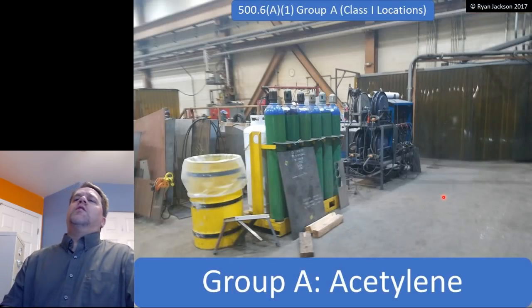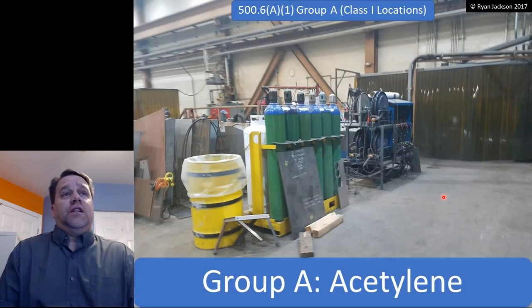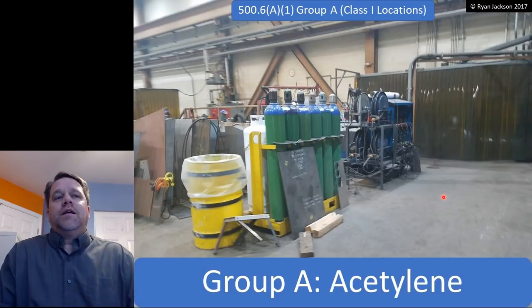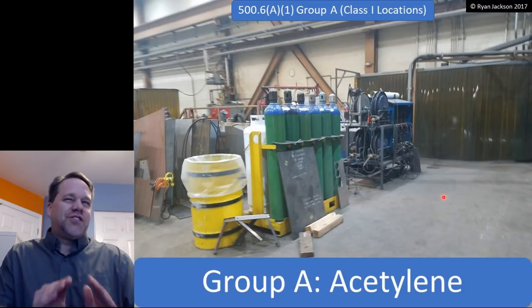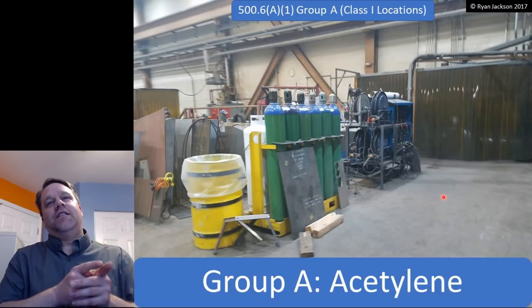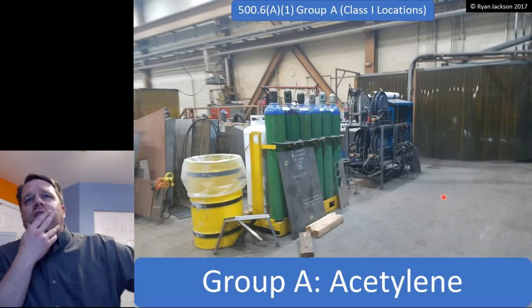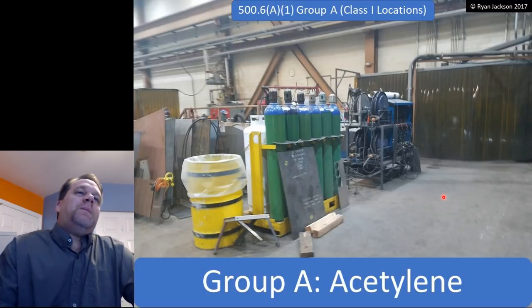So what are the groups? Well, Group A is very simple. Group A is acetylene, and nothing but acetylene. The only Group A chemical compound is acetylene. Now, almost everybody that's spent much time in hazardous locations has looked at an oxyacetylene welding system and thought, boy, is that a Class 1 location? Well, let's think about this.